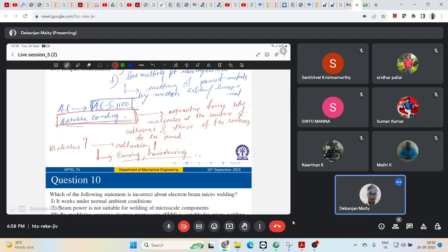And this curing can be done at some temperatures, again it depends on different adhesives. So mostly they range from 130 to 150 degrees C. Within those temperatures, you have to provide some time to cure the material, right? And here, like brazing or soldering, the thickness of the adhesive should be minimal, less, to provide a strong bond, right?